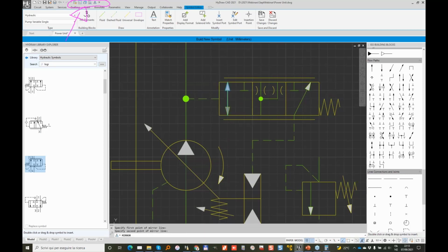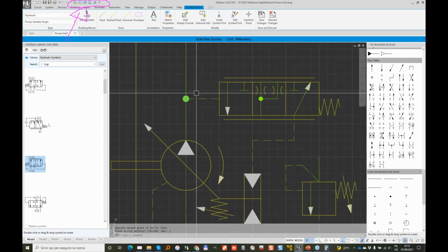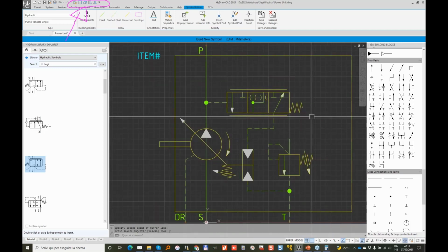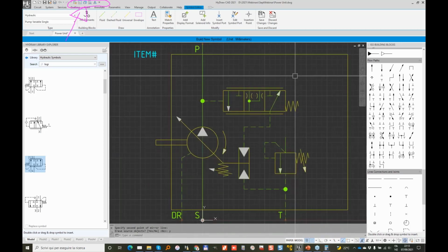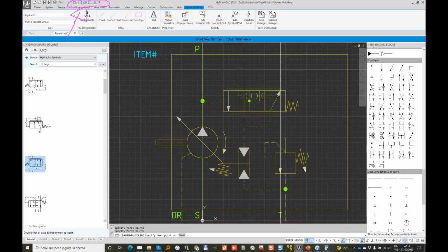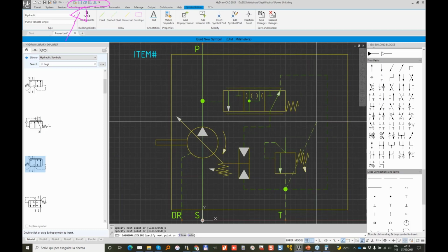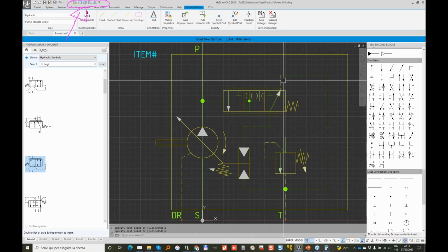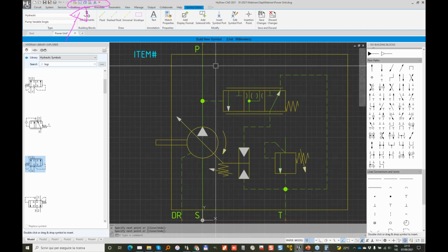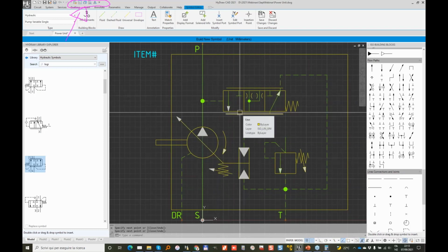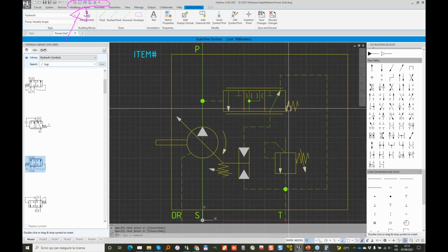This line is going to the tank. So we do a connection to the tank. So by default, tank line and tank line on the swash plate, the spring is winning and keeps the maximum displacement. Now we need to make the pilot on our pressure compensator.